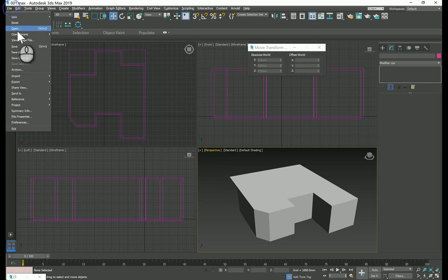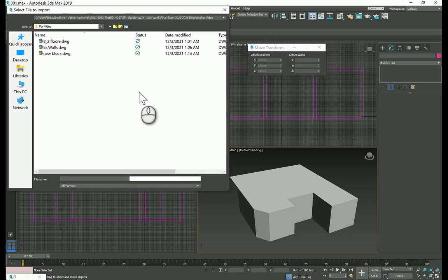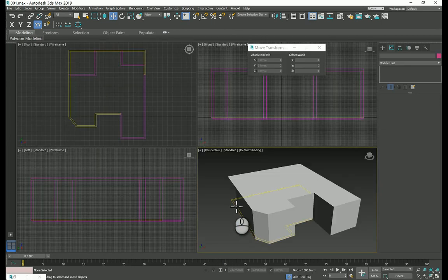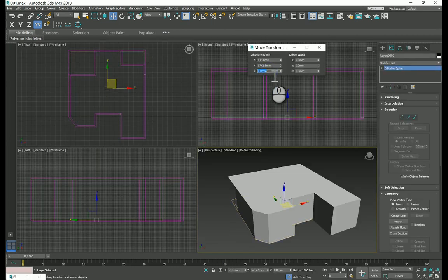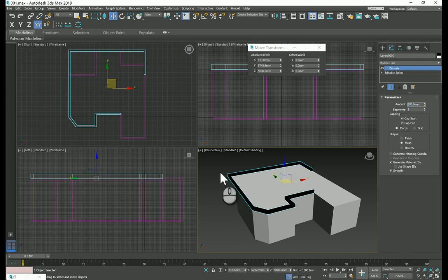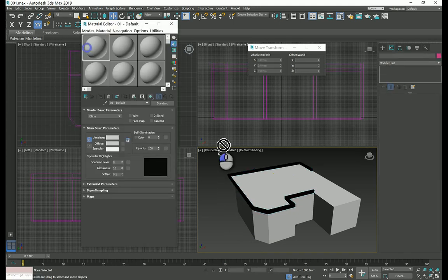Okay, something wrong in here, but I'm gonna follow that anyway. So new block, hit OK, select this guy and make it 5,000. Okay, and then I'm gonna paste the extrude, which is a minus 200, and I'm gonna fix that to make it 500. So the top of that parapet should be 5,500, as you can see.